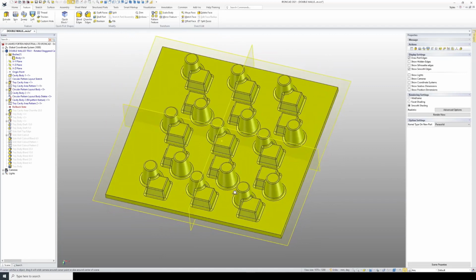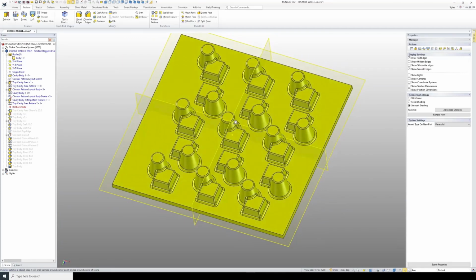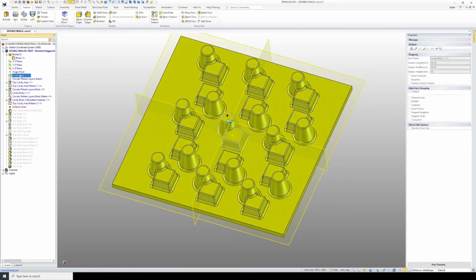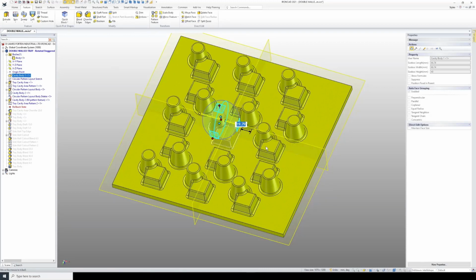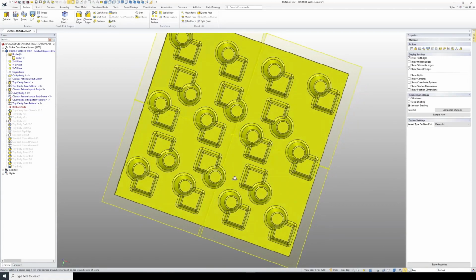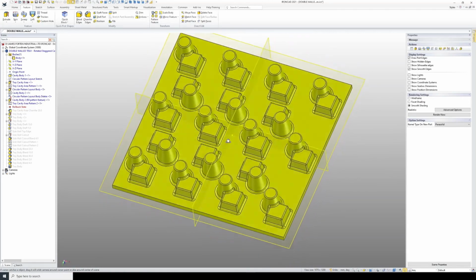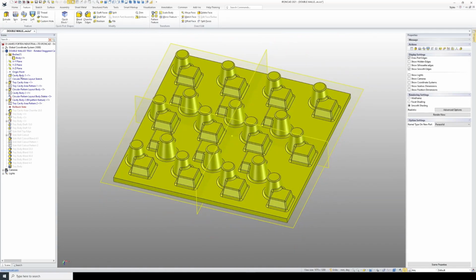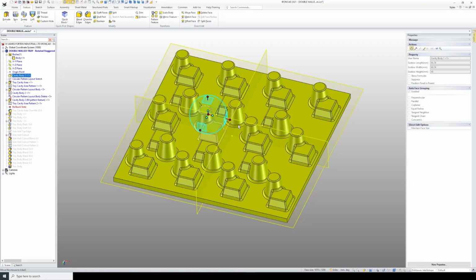Now to better populate that, again, this is all being driven by the position of the original cavity body. So I've got it selected, got the triball. Let's say move this 48 millimeters to see how everything recalculates, and so that looks as though that's a better use of that area. I'll select that body again and I'll move it back to 0, 0 to where it should be.